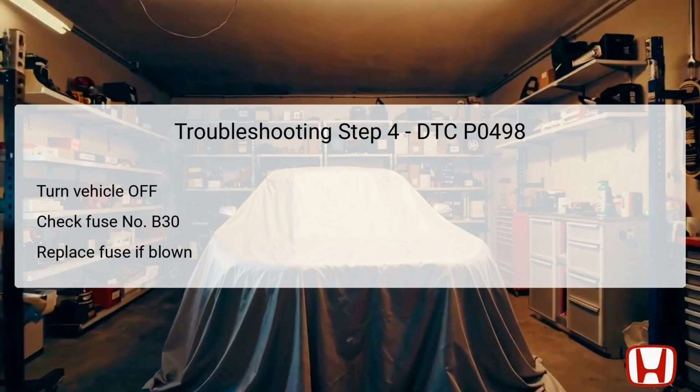To verify the integrity of the electrical supply circuit, turn the vehicle ignition to the off lock position. This ensures safety while investigating electrical components. Next, locate and inspect fuse number B30, located in the underhood fuse relay box.